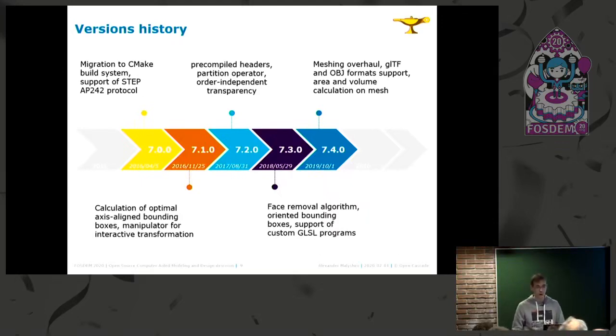7.1. The Open Cascade technology usually uses bounding boxes to perform fast intersection checks. Sometimes, especially in the case of B-splines, these axis-aligned bounding boxes are much bigger than nominal geometry. And there's a problem. For instance, when we can compute a bounding box once and cache it, it's much more interesting to build an optimal bounding box than an ordinary bounding box. Unfortunately, we sacrifice performance for that, of course. Calculation of an optimal bounding box requires more effort.